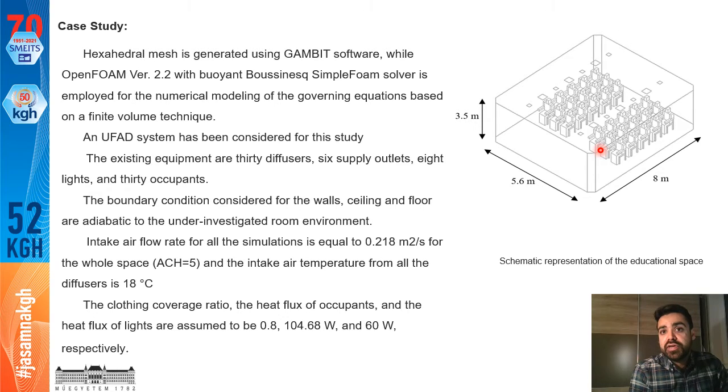So we have used the underfloor air distribution system. The abbreviation is UFAD, and for that we have used a hexahedral mesh, generated using Gambit software, while OpenFOAM version 2.2 with the buoyantBoussinesqSimpleFoam solver is employed for the numerical modeling of the governing equations based on finite volume techniques.